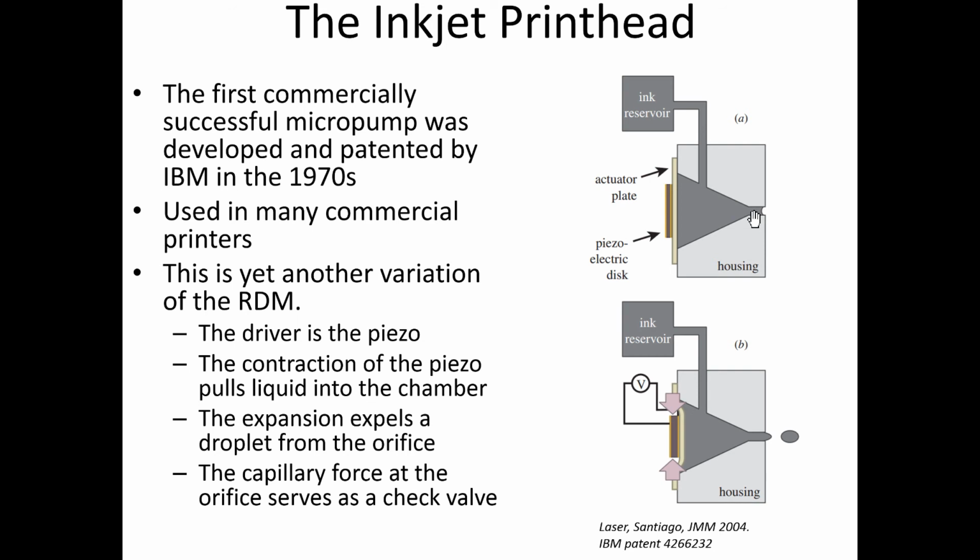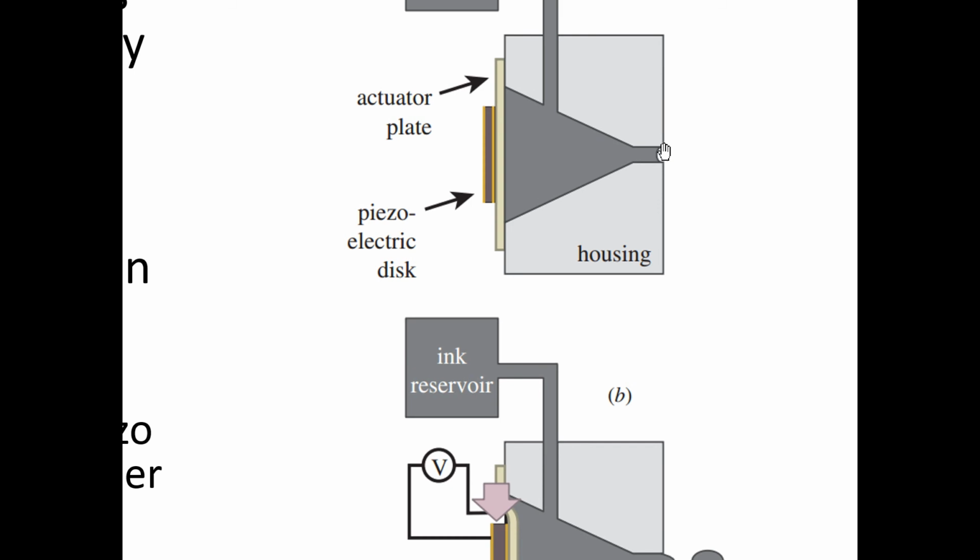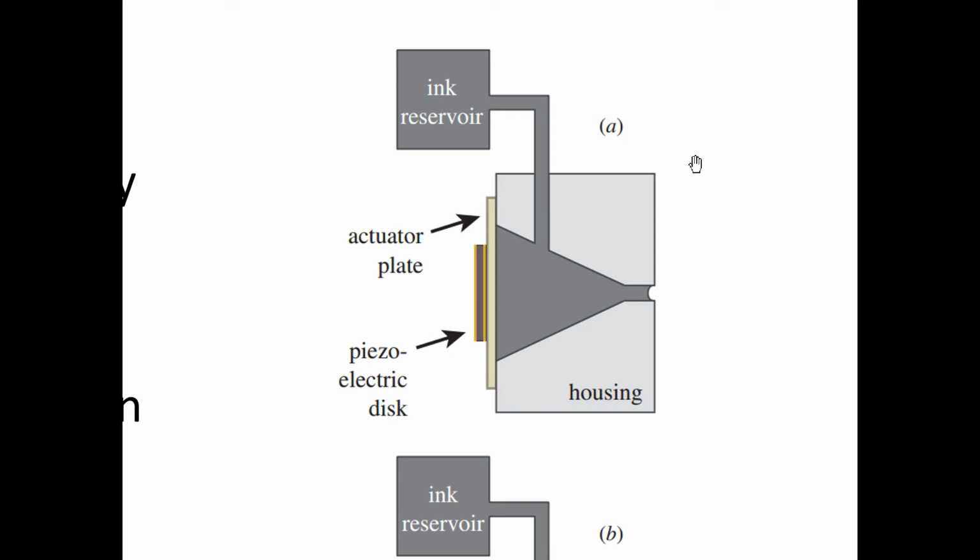Whenever you see a concave direction like this, you can see that the water likes to be at the edges. It likes the material that it's in because the water is building up at the edges. So the water molecules are going to tug on the other water molecules here, and that generates a capillary pressure going from left to right. It's going to try to pull the liquid from left to right, so the capillarity acts as a valve.